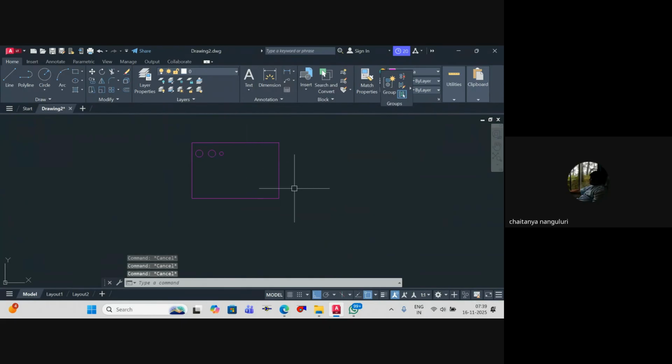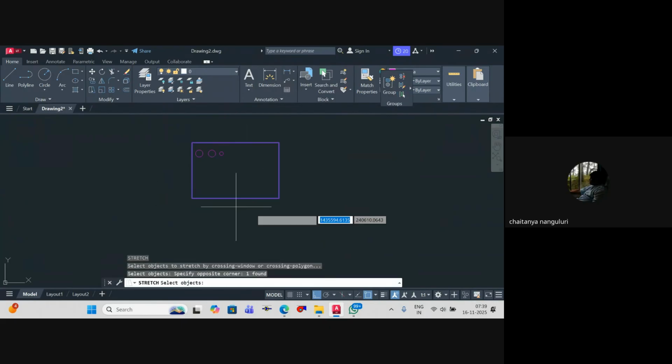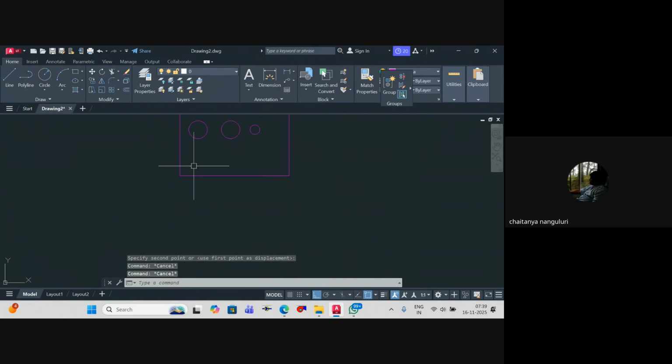So let's say you have a very small shaft, we'll keep everything exposed. So your hydrant riser could come here or you take it outside. It's up to you if the shaft size is smaller. If you want to conceal everything, then 1.2 by 1.8 is comfortable.